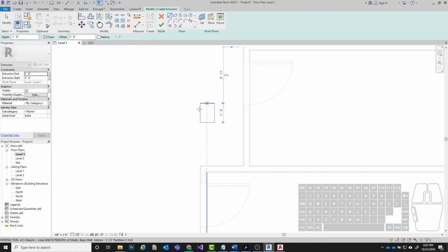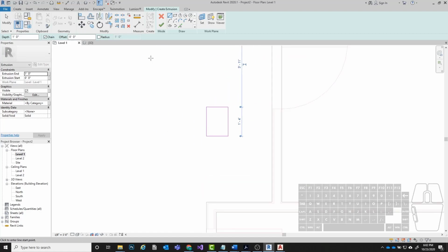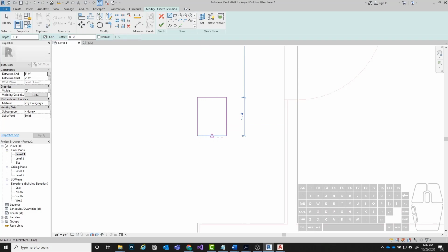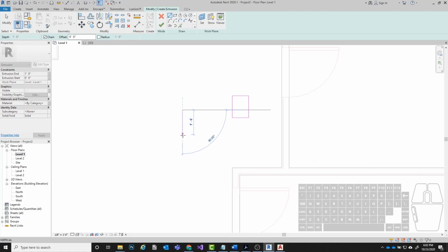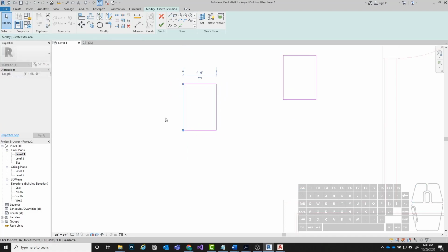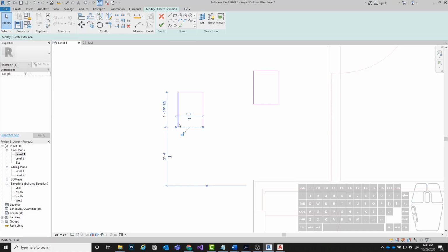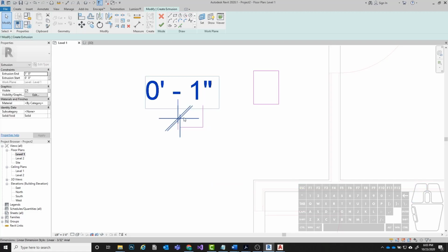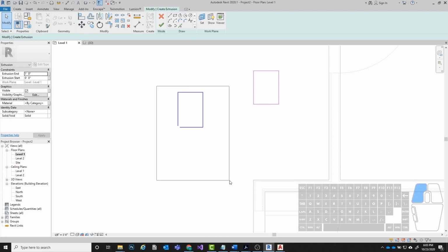Now we have a shape that's drawn in here, and it's a perfect rectangle. Make sure all of your intersections are connected properly. This isn't going to work if for some reason you have something like this where you have a boundary that is extending beyond. All these have to be perfectly aligned with one another at the intersections, okay? So you want to avoid weird things like that, or little gaps at the corners. All right.